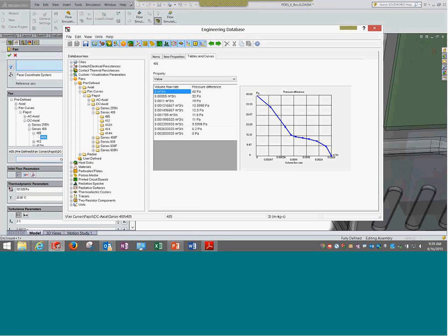If I show you, it might look something like this. It goes like this, and there will be a point somewhere around here at which the fan is expected to work at the highest efficiency. At that particular pressure difference, if the system can work there, the flow rate can be maximum or appropriate, and the fan is used to its complete efficiency.